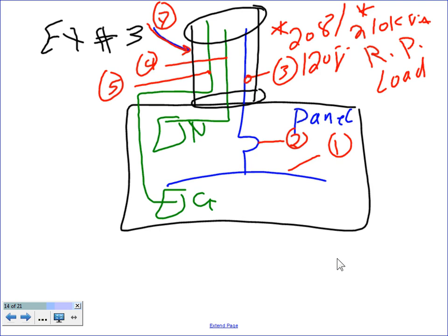Oh, right here, I have a 210 kVA load. Now, how did I come up with this load? I took 180 volt-amps times the receptacles in my building, then derated them: the first 10K, leave them alone; anything higher than 10K, cut by half. Remember, guys, how we did the receptacle calculation? I demanded this load and came up with this lump sum 210 kVA load.